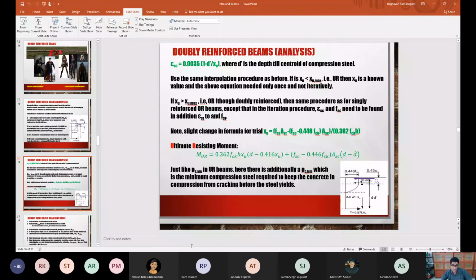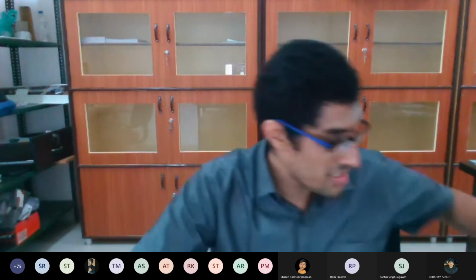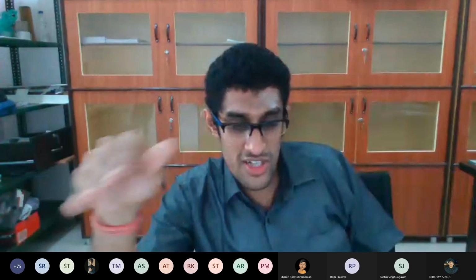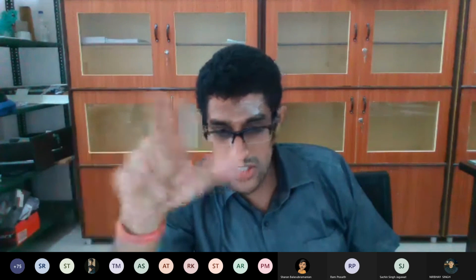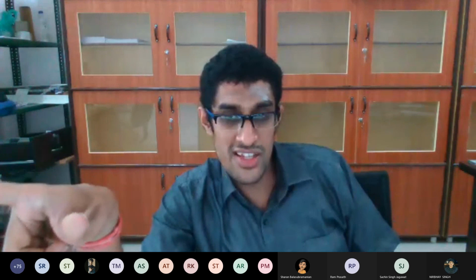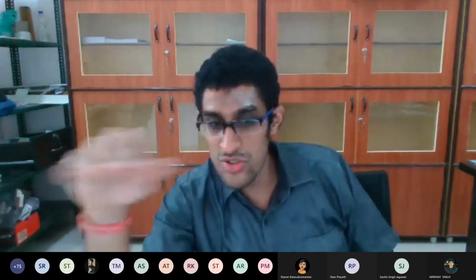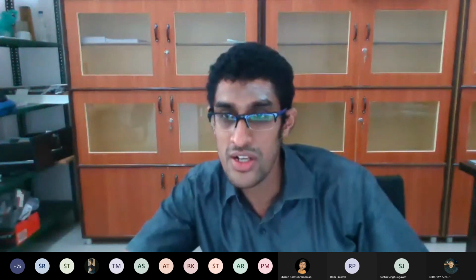Till then, please open your codebook IS456. Your task till next Wednesday is to open IS456. Open the contents page, the table of contents. See where limit state of collapse is, and within limit state of collapse, see where the clauses with respect to beams are. Please go through those provisions. You will find a lot of things which were discussed in today's class. So that is your task for the weekend.